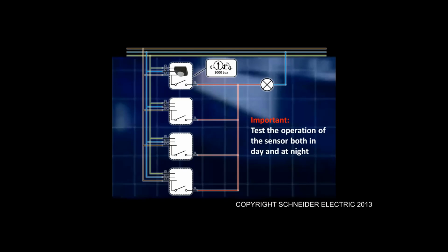What you need to do after that, and this is only once you've confirmed the operation of the first sensor, is connect up a second sensor and go through the same process. And what you should find is, as you keep on going through adding sensors, you know that every sensor you've added before should be working 100% correctly.